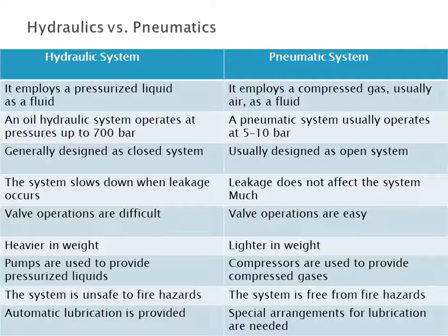Okay, so generally the hydraulic system is designed as a closed system. It means there is no leakage. If there is any leakage, then the pressure will decrease or you will not get the efficiency of the system. In the pneumatic case, usually it is designed as an open system. So you can say that the air is sucked from the atmosphere, and when the work is done the air is released to the atmosphere again.